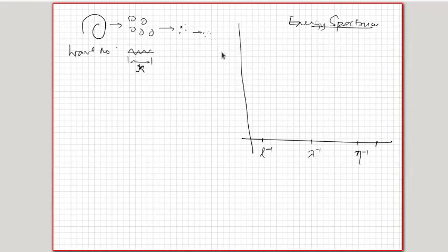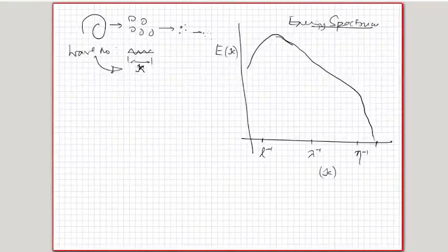So what has been found is that if I say what is the amount of energy that is present in the eddies of that size kappa, this kappa is different from the von Karman constant that we looked at. This is basically the wave number. Okay. So the number of oscillations created by these eddies per unit length. So these will have very few, so the small wave number. These will have very large, so the high wave number. So what is found is that the spectrum looks something like this, then it becomes a straight line in this region, and then it goes like that.